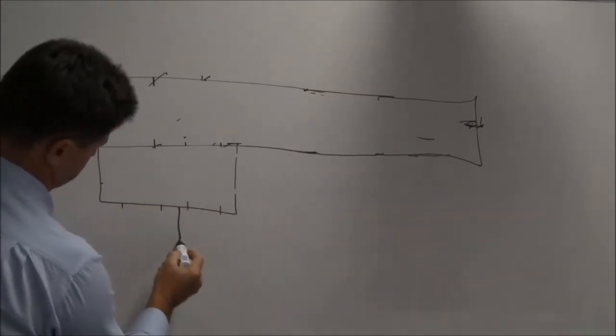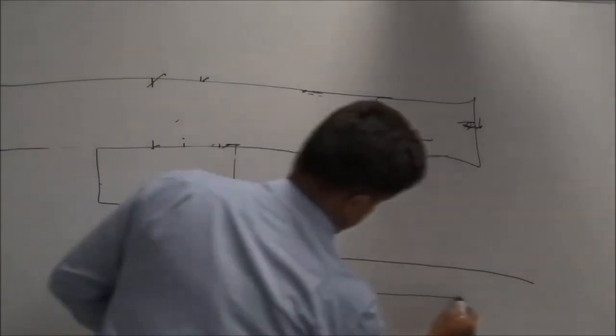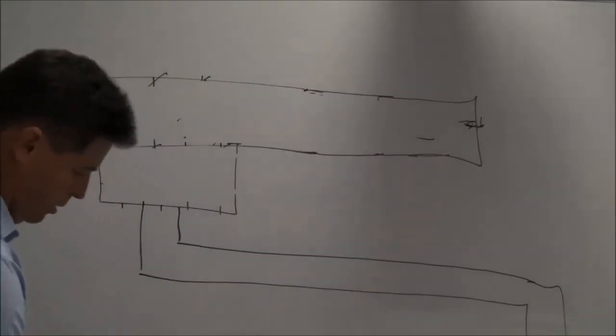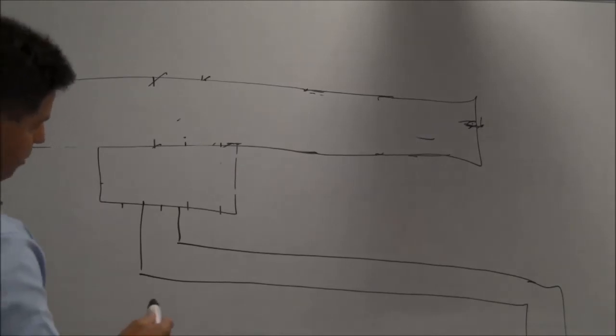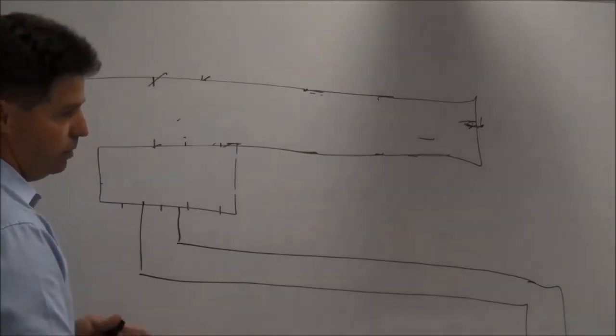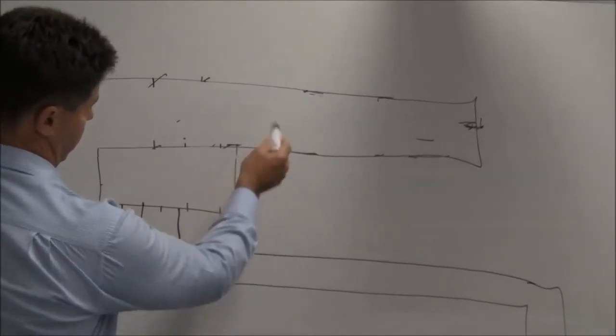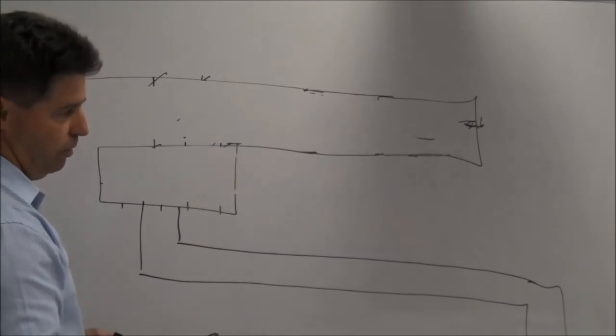He's run out of his gutter all the way along in the building and then dropped down the building. Nothing wrong with it, all works fine. What you need to be aware of though is the losses inside that pipe when you do that. If you don't, the losses could be enough that you're actually then overflowing that gutter.